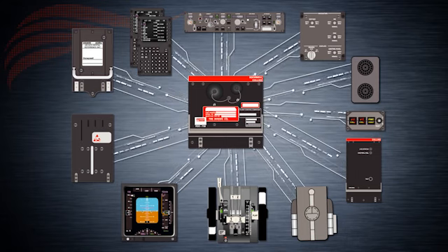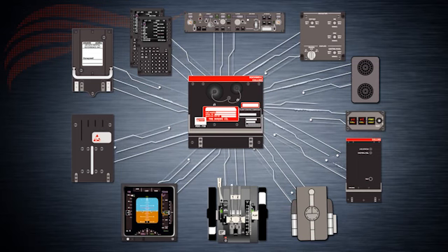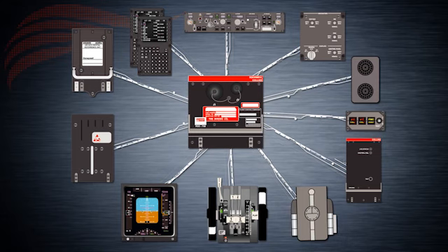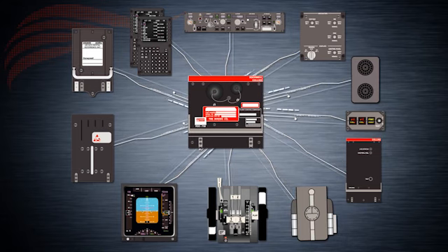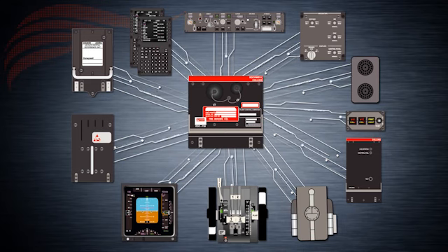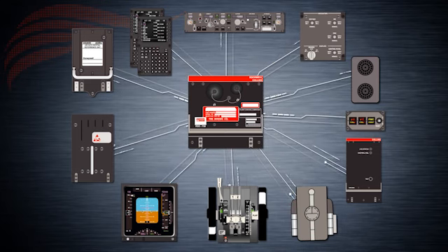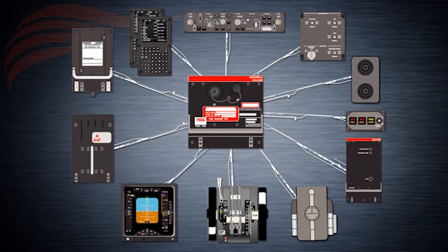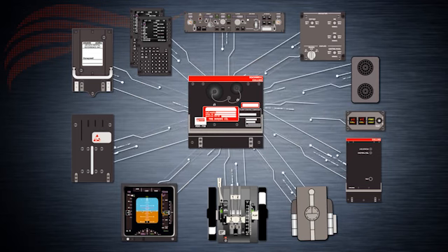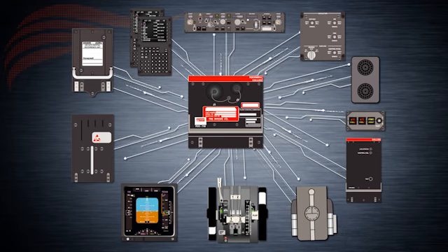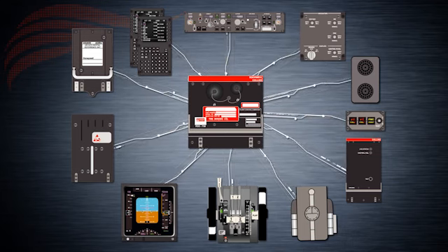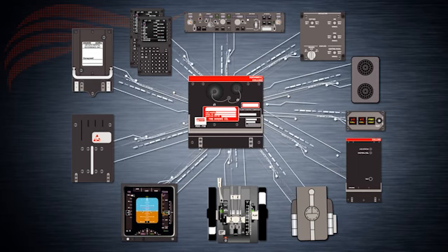All that said, from this image, you can tell that the FCCs take a tremendous amount of information, sort through that information, and send it back out as needed. Again, it can't be stressed enough that without this essential central hub, which we referred to as the conductor of the symphony, these components wouldn't have a way to communicate. It takes a central location for processing to make sure that the information input by the pilots to the MCP, autothrottle, and FMCs turn into control movements, smooth automated flight, and successful navigation.